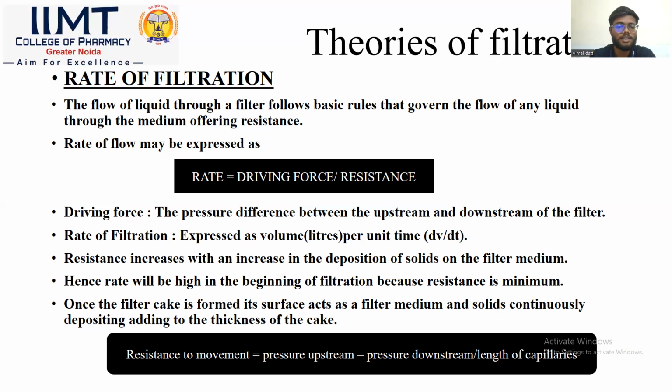And third one is resistance. Resistance increases with an increase in the deposition of solid on the filter core. So as much as our solid is retained on the filter core, it will increase the resistance over the filter medium. Hence, the rate will be high in the beginning of filtration because resistance is minimum, and it will be less at the end of filtration.